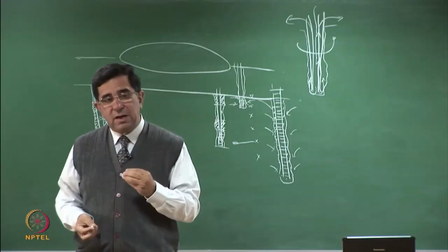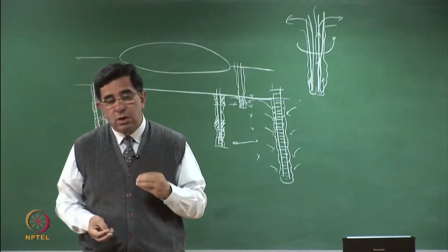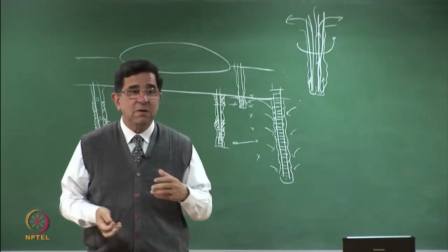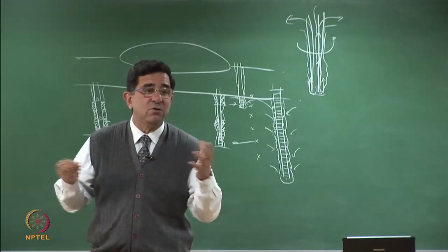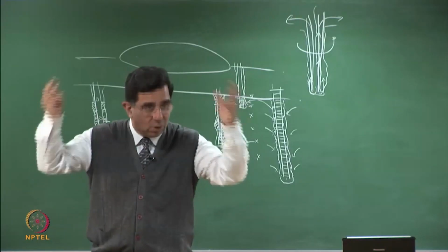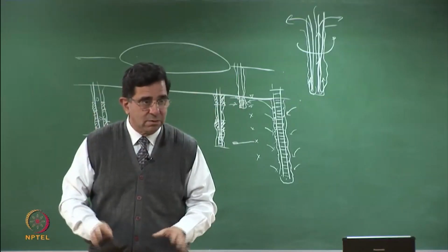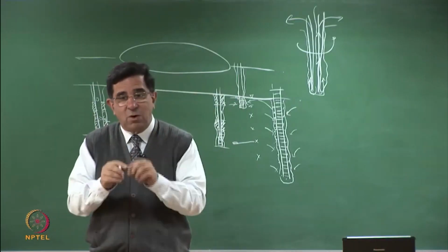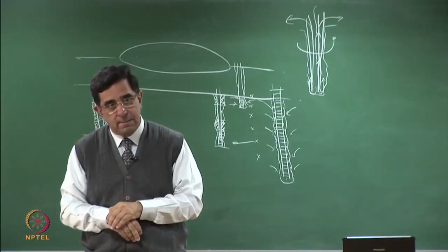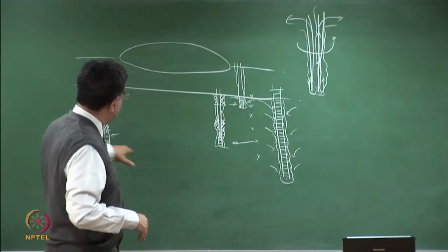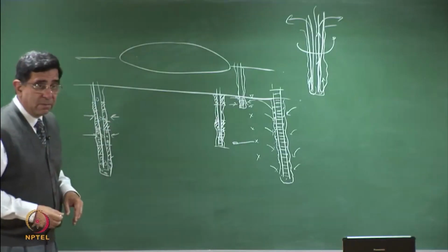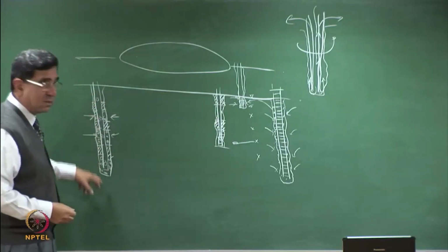So basically, that is how you seal the hole, especially for applications like ours. Please understand, in a normal well, you are not trying to stop water from coming in from every level. You want water for drinking purposes or irrigation purposes. You want all the water to come in. Is that right? Here we are saying we want water from a specific place. Therefore, this sealing becomes so much more important. So a multi-port device has multiple seals, and then you will say, sir, but still in this it can get mixed.